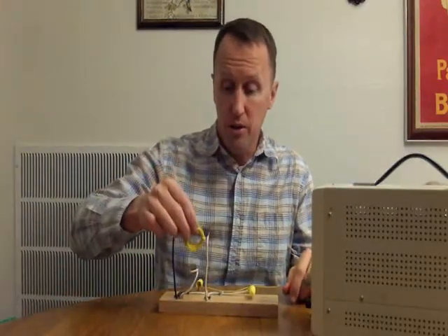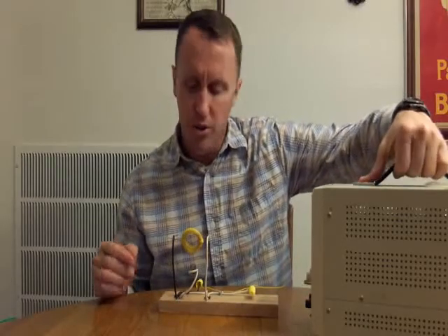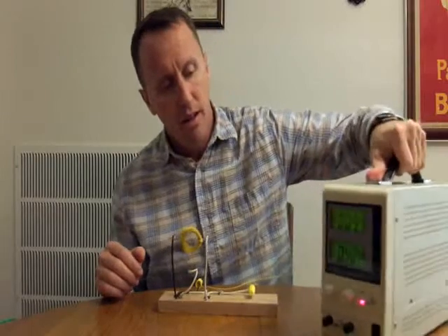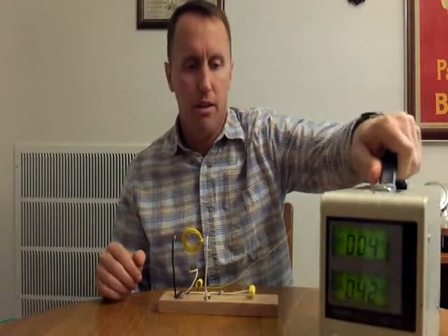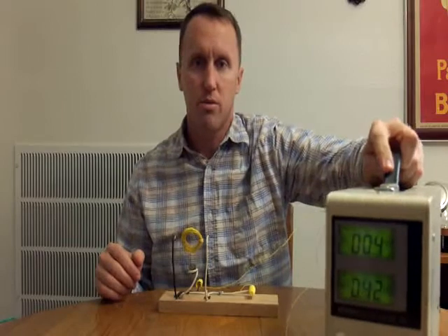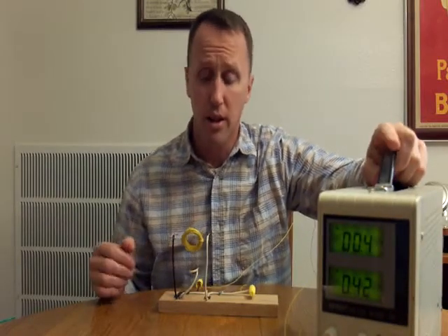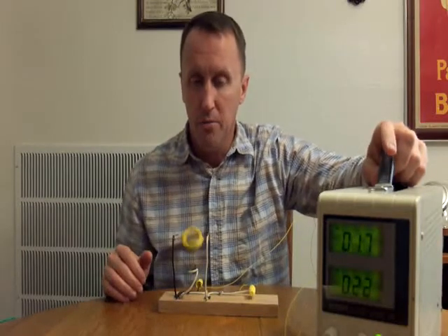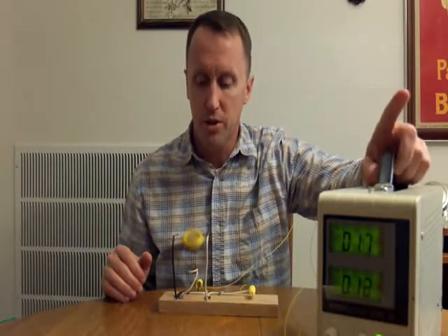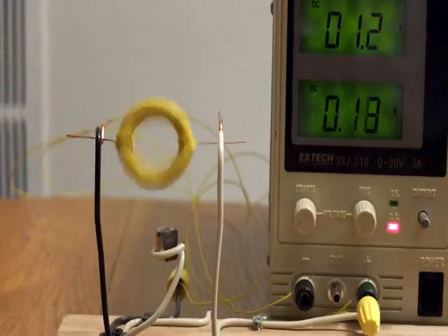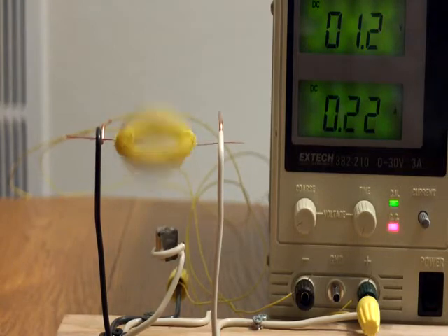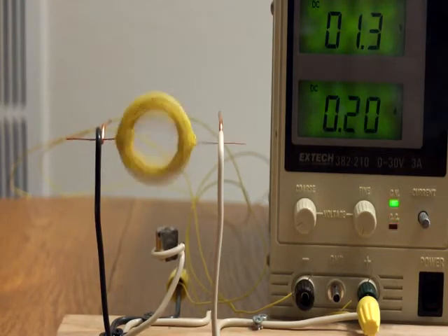Starting with a 30-turn coil, I'm going to demonstrate a property that all of the coils exhibit, the 30-turn coil especially: prior to starting, the current is about twice what the steady-state current ends up being, and the voltage is considerably lower. As I start the coil turning, the amperage drops, the voltage climbs. It's going to fluctuate because the circuit is turning on and off, so what we see on there is basically an average current as a result of the on and off state.